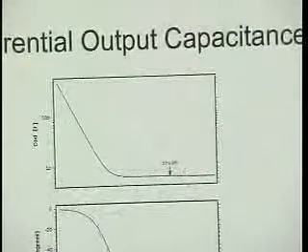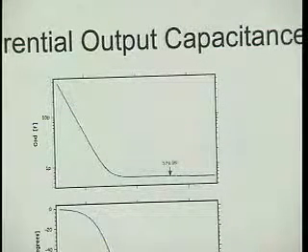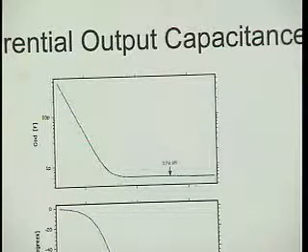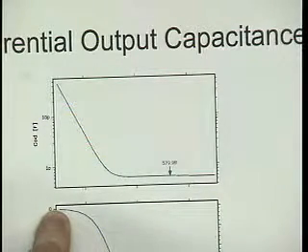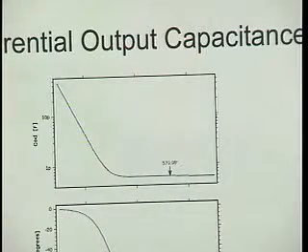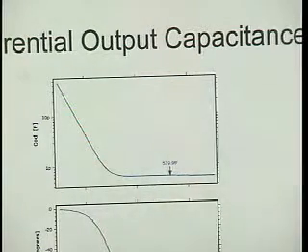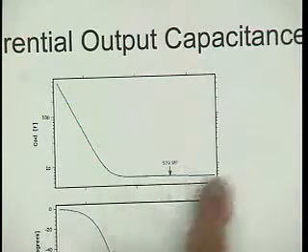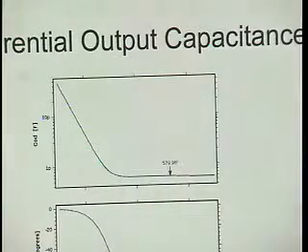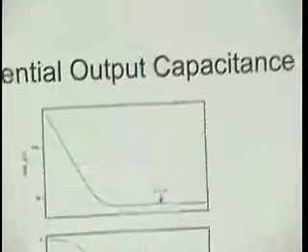I can measure the differential output capacitance I just mentioned. So I also see over which range it's actually capacitive or not. Right? At very low frequency, of course, it doesn't look very capacitive because I have the R out. That, after all, is finite. And then at high enough frequency, the amplifier sort of gives up its ghost, and the capacitance dominates. About half a picofarad, almost 600 femtofarads hanging there on this amplifier. We have to look at the devices, but certainly not to ignore, right?